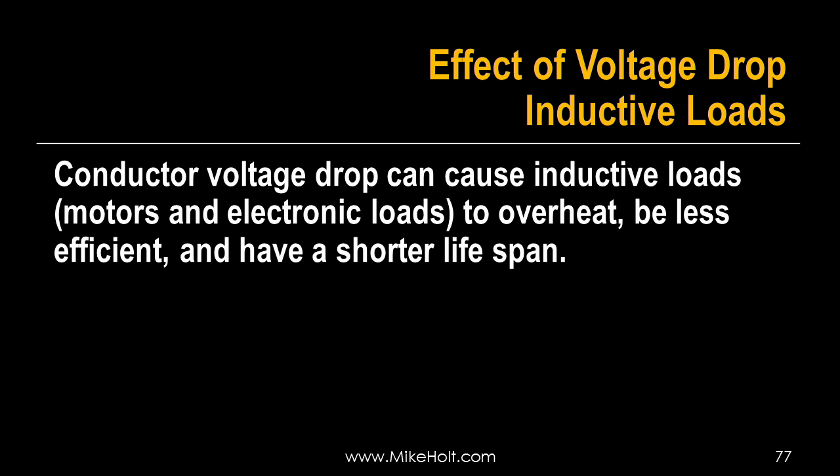An extreme example of a voltage drop: I was doing some work at my house. I purposely was trying to design something so that I could lose the neutral to the building, but use the earth as a return path. The result was the voltage on my circuit that had my electronic ballasts wiped out 3 of the electronic ballasts. I had not considered the effect of extreme voltage drop on those electronic ballasts.